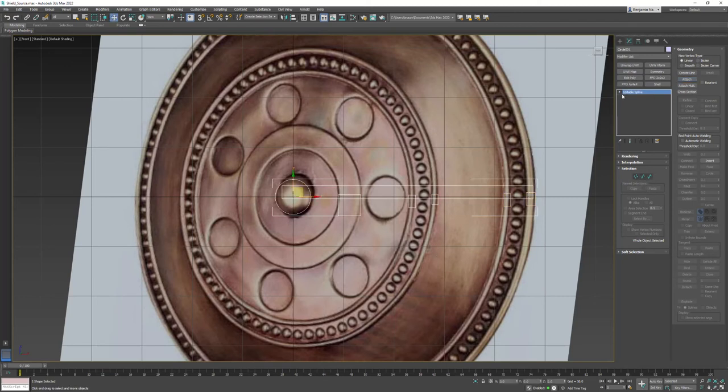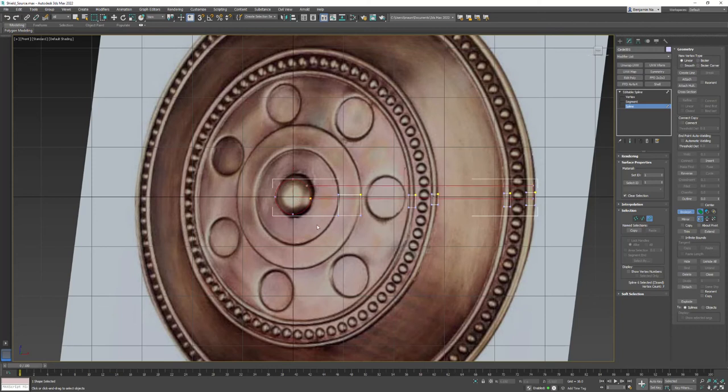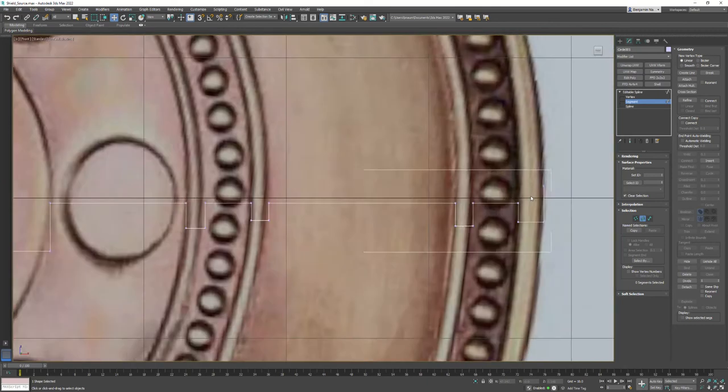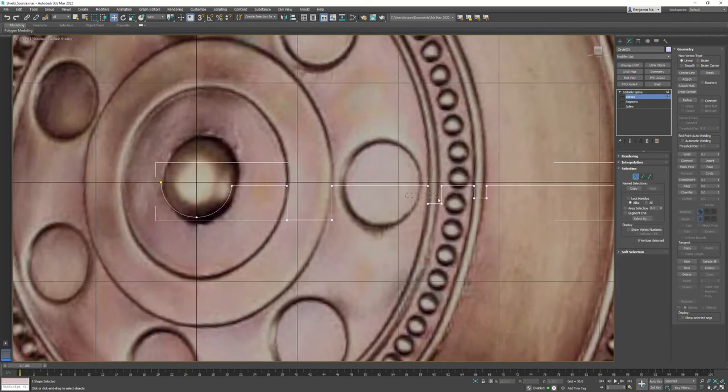Now, as we have previously with splines, we're going to come in here and under spline, we are going to select the main circle part, and then we're going to start using Boolean here under geometry. So we've attached these elements together, and now we are Booleaning them together to make them one continuous spline. Let's go into segments, and we'll get rid of all these extra segments up on the top because we really just need what's on the bottom here. All right. And so now from here, we can start coming in and adjusting shapes.